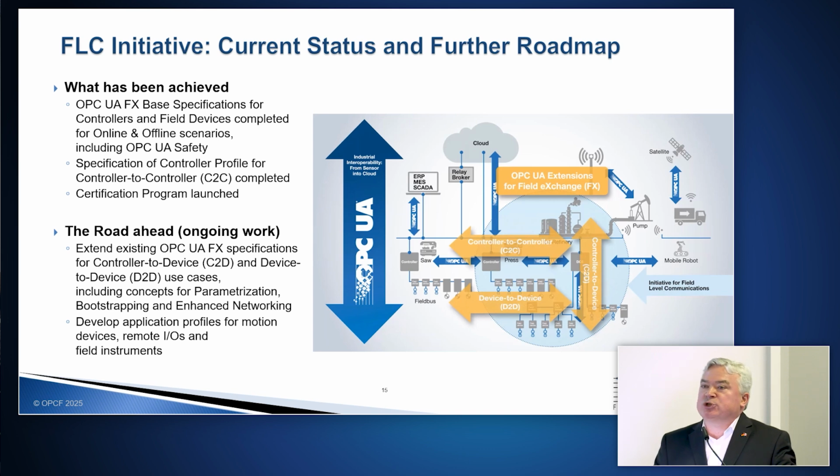We have some additions to the spec with regard to, for example, parameterization, how controllers parameterize all the field devices, how to do the bootstrapping, how to, let's say, boot up the complete network with controllers and field devices, and some enhancements to the networking that we need for some of the more sophisticated application areas.